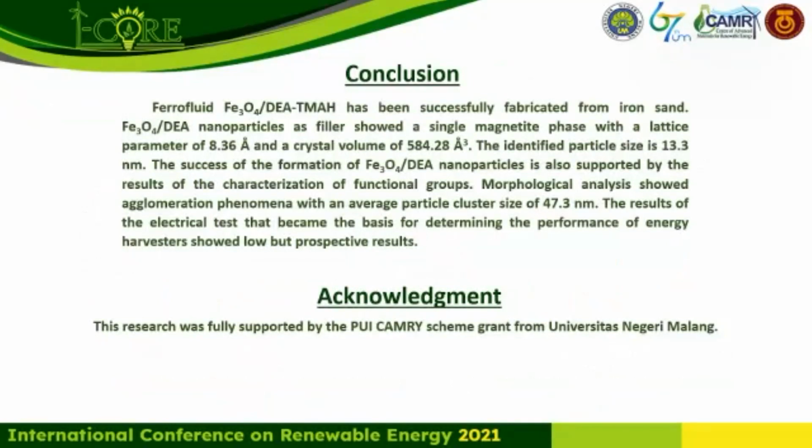So the conclusion is ferrofluid magnetite diethylamine tetramethyl ammonium hydroxide has been successfully fabricated from iron sand. Magnetite diethylamine nanoparticles as a filler show a single magnetite phase with a lattice parameter of 8.36 Angstrom and a crystal volume of 5,084.28 Angstrom cubed.